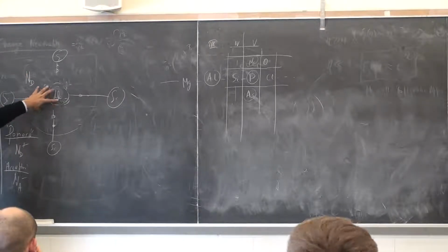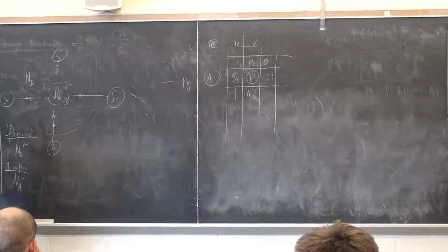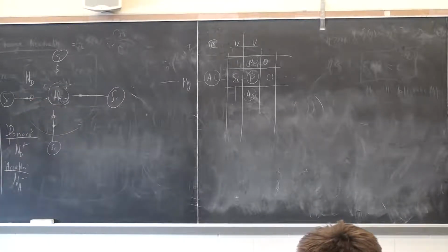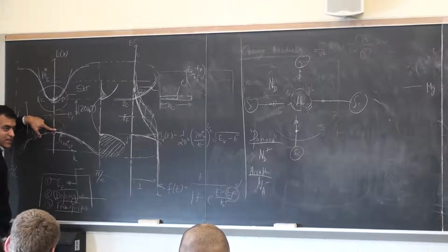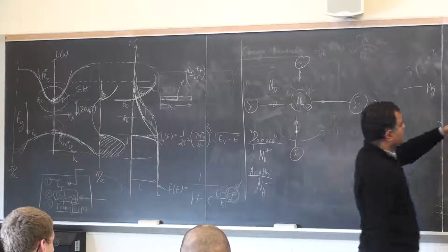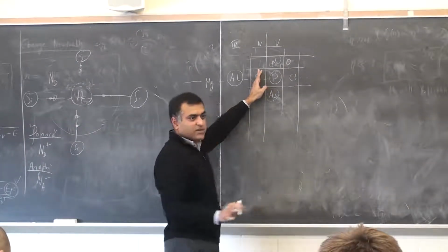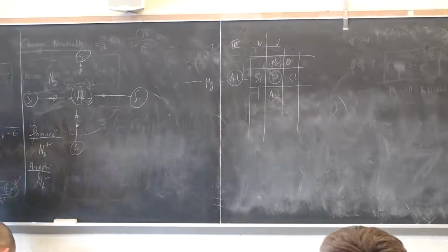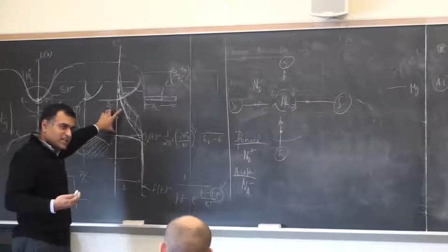So this picture is substitutional doping, and if I just substitute an oxygen here, let's see, let's say I bring in oxygen, and oxygen has all these atomic levels. Let's say oxygen had a level here. Though it's on the right side, it is possible that it can break this rule that I told you, that it can dope something n-type. But more generally, it is something else. This picture of a shallow donor is not what is in operation in oxygen and silicon. And does oxygen really dope silicon n-type?